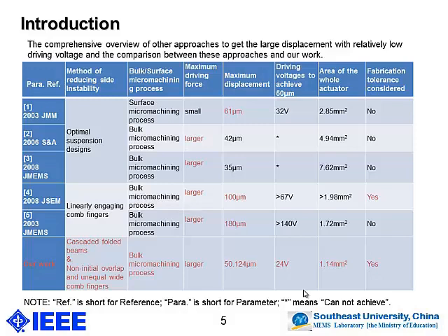Compared with the others, the maximum displacement of our comb-drive actuator design is not the largest, but we get the smallest driving voltage to reach more than 50 micrometers, and the area of our design is the smallest. The fabrication tolerance was also considered.